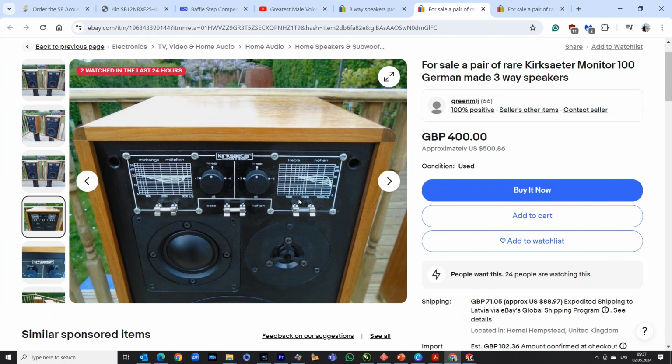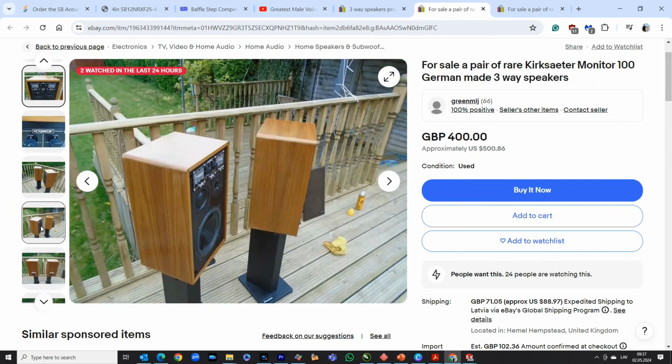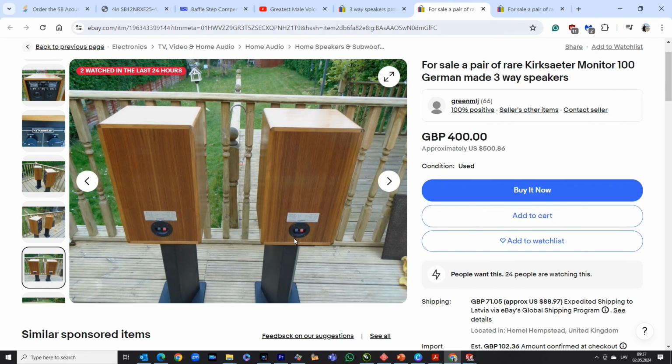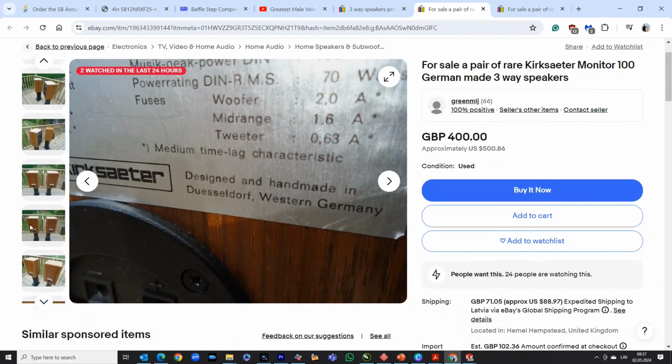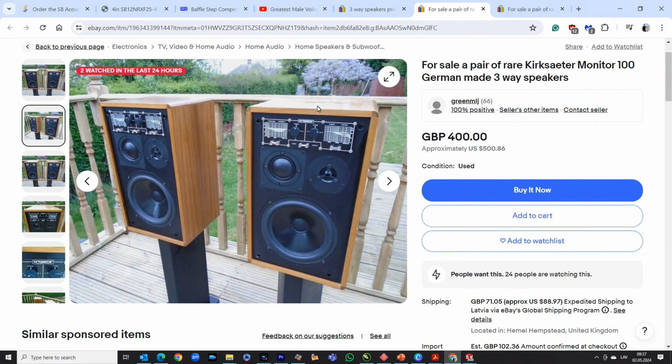At some point I had a problem with that. Good candidate. And look, if you replace that input with some adapter plate and an 8-pole Speakon connector, you can make those speakers passive, and I think the woofer here is excellent and well made.